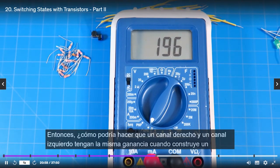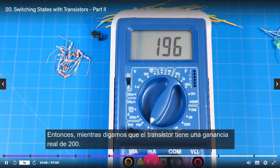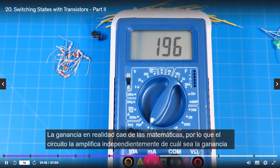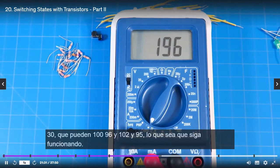When you build an amplifier, we use what's called negative feedback, and we design the circuit such that the actual gain is irrelevant. So as long as, say, the transistor has an actual gain of 200, we never use it more than say 10 or 20 or 30 times. And we use a feedback circuit, so when you do the math, the gain actually falls out of the math, so the circuit amplifies regardless of what the actual gain is, as long as you don't exceed the gain. That way, as long as both transistors could do, say, a gain of 30, which they can, 196 and 195, whatever, it'll still work.